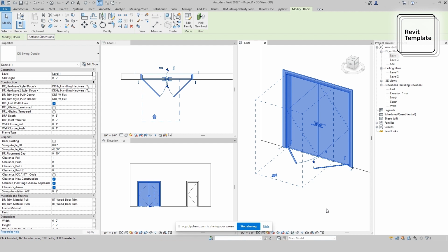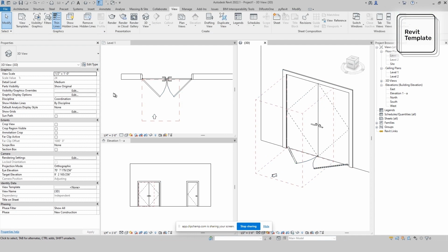Second, given the family's modeling method, this means the hidden object will no longer report inside of a schedule and affects the overall counts. Thirdly, setting up the visibility parameters knowing this will require a very detailed model and ultimately will not be user-friendly and will require extensive knowledge to modify and processing power to adjust. This is why we opted for object styles and visibility graphics to adjust all settings.